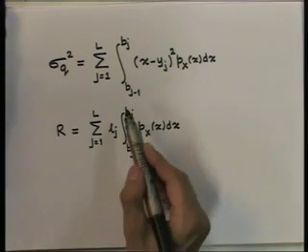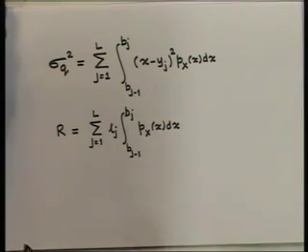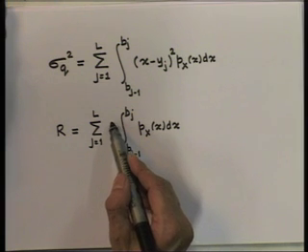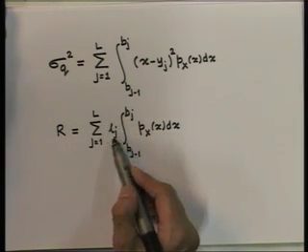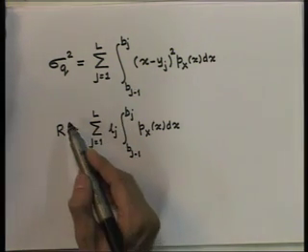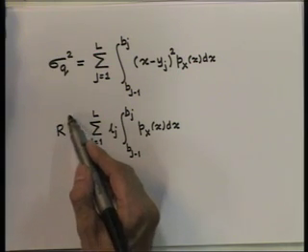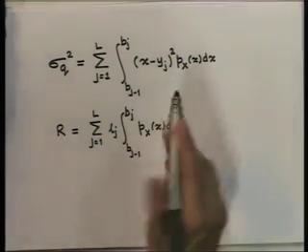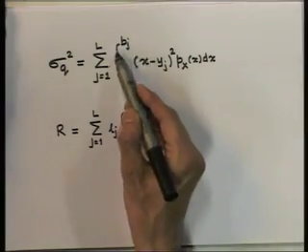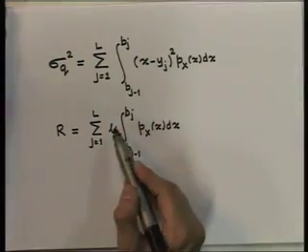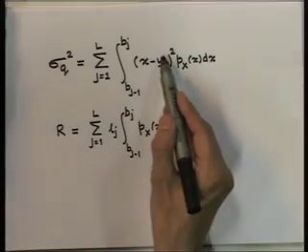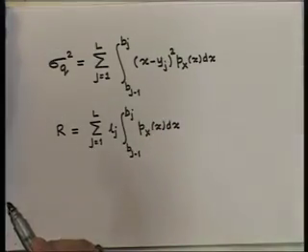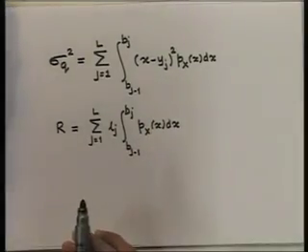And the partitions we select and the binary codes for the partitions will determine the rate for the quantizer. Thus, the problem of finding the optimum partition, codes and representation levels are all linked.